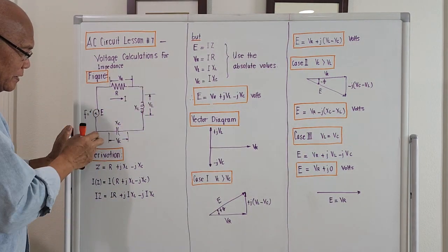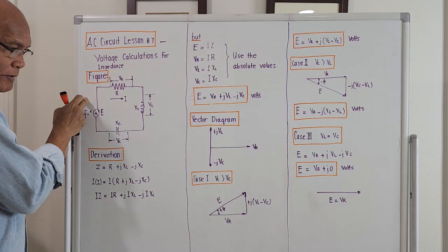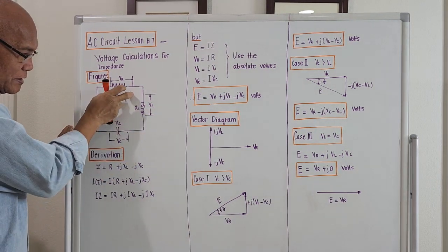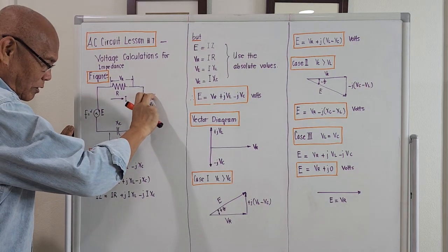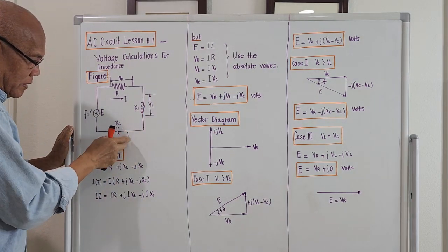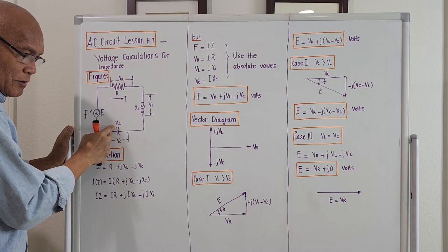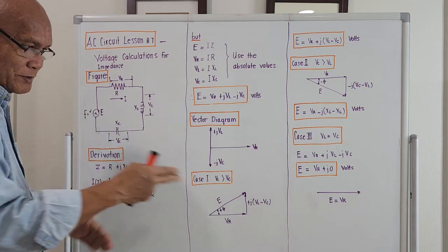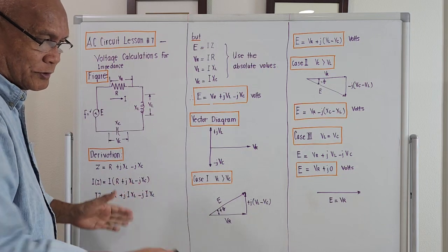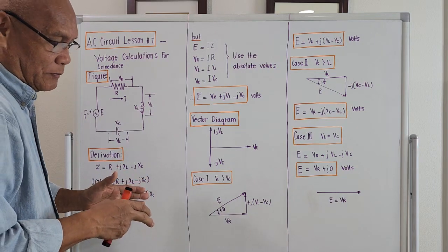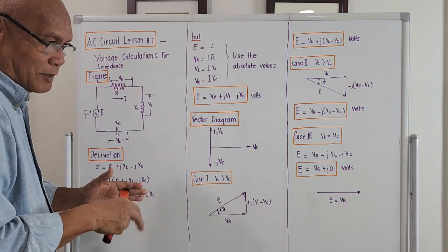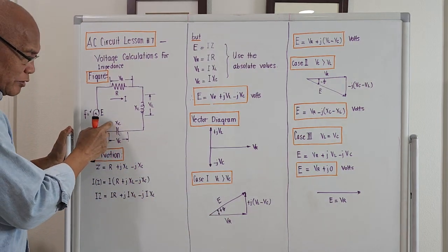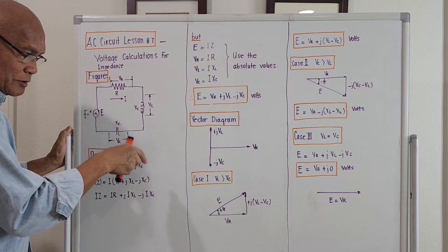We are given a voltage source here, and the impedance connected is a resistance, a coil or a motor maybe, an X sub C, a capacitor. It could be a synchronous motor that is overexcited, and it is to be considered, meaning the current of that will be a leading current like an X sub C. So this X sub C here could be a synchronous motor that is overexcited.